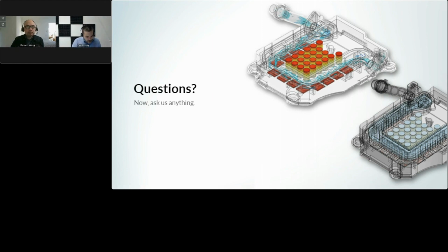Now, to the question of SimScale, SimScale does not come with a vast material library such as are available out there, like MATLAB or other material libraries that aspire to be really complete and give you a lot of fine granular atomic choices around materials. That's not the case in SimScale. So what typically happens is that customer organizations upload their own and store and share their own material information within SimScale. That's the typical workflow, or the typical way we're seeing people define material data on SimScale.